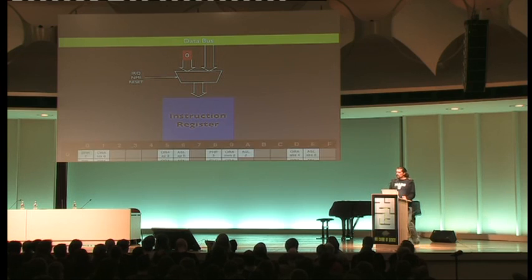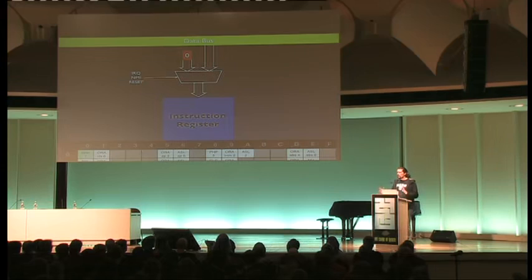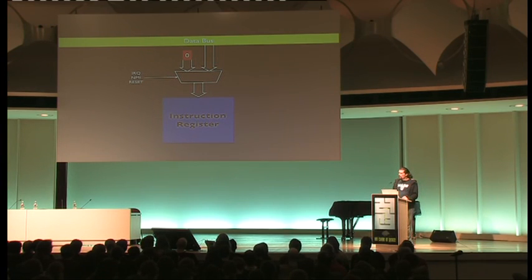And the 0, you might remember, is the break instruction. So this is a really neat trick, injecting a break instruction which does the whole sequence of what's going on, but afterwards it has to clean up and do the right vector and has to put the break flag properly and everything. So it has to cache that information somewhere, but the sequence is done with the break.